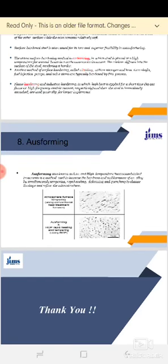And last is ausforming. Ausforming, also known as low and high temperature thermomechanical treatment, is a method used to increase the hardness and toughness of an alloy by simultaneously tempering, rapid cooling, deforming, and quenching to change its shape and refine the microstructure.